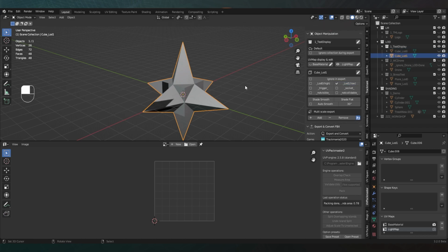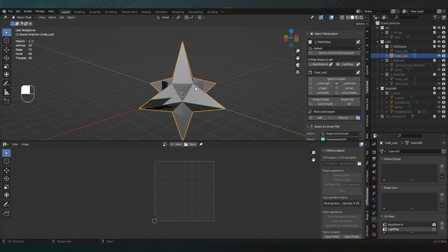Okay. So, yeah. How do we effectively use this technique for our items? So key to creating LODs is basically simplifying your high poly mesh in order to reduce the poly count. In this case, I of course didn't reduce anything. It was just to show you that there is indeed a difference. But yeah, we want to give our GPU an easier job of rendering. So of course we will have to reduce a lot.